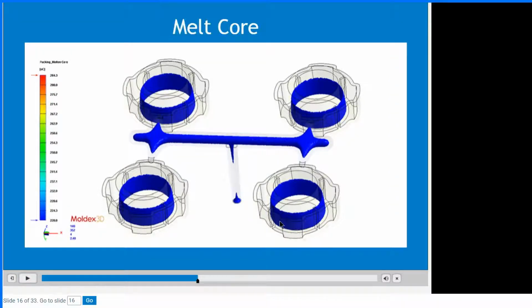All the translucent areas are frozen at the same time increment, but you see this very thick wall here in the center that carries a lot of heat. So if we know that we have areas in the tool that carry a lot of heat, that means the mold maker needs to know this to take care of these hot areas with potentially some additional waterline layout, some larger sizes, or some special steel. Okay, let's take a look at how to do this.